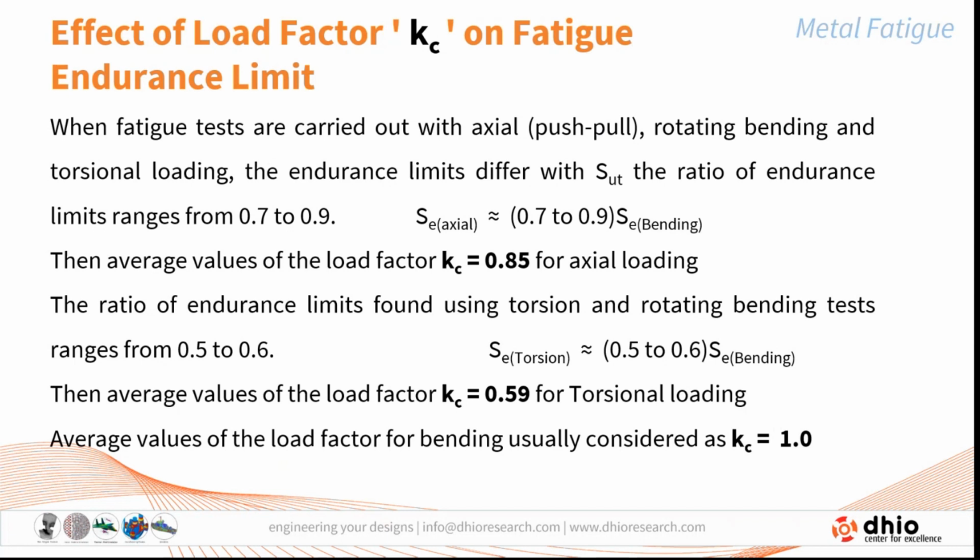Then the load factor. When fatigue tests are carried out with axial push and pull, or rotating bending and torsion loading, the endurance limit differs, because the standard specimen is subjected to rotating bending. The ratio of the endurance limit ranges from 0.7 to 0.9. Thus, Sc, that is axial, varies from 0.7 to 0.9 times the endurance limit of the standard testing specimen. And thus Kc becomes 0.85, usually taken as the average for axial loading.